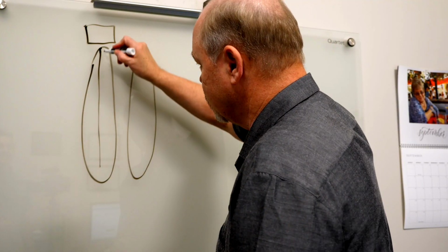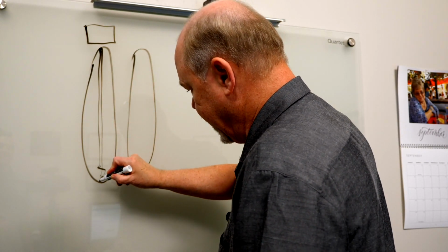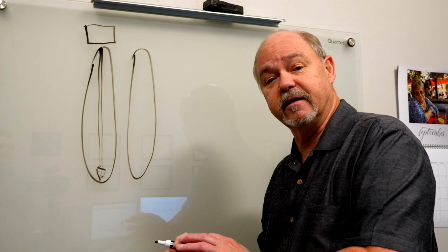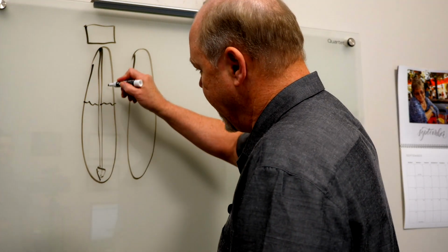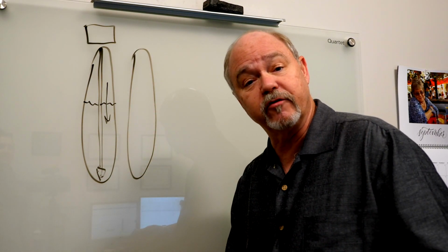You have a distributor or riser tube, if you will, and down at the bottom is a distributor basket. This distributor basket is where the water flows into after it passes through the media, which is typically about halfway up. As the water flows through this media, we're getting our pH adjustment.